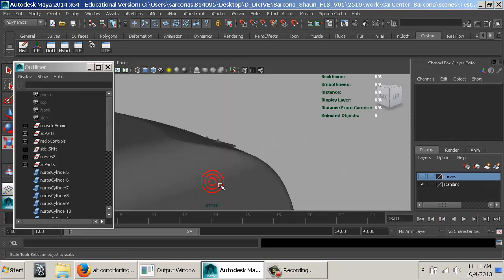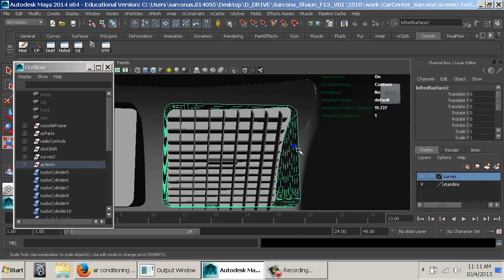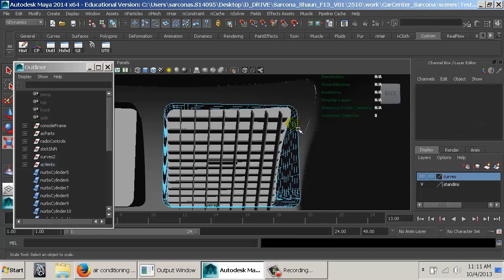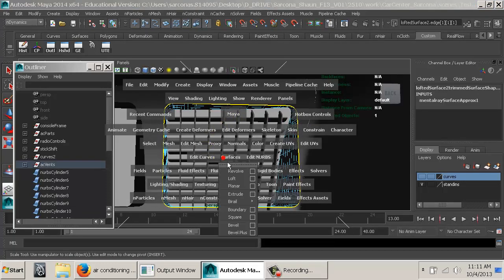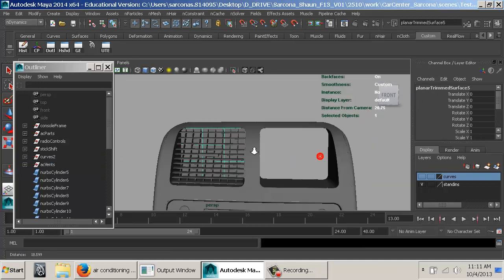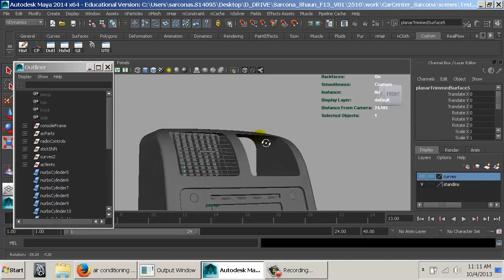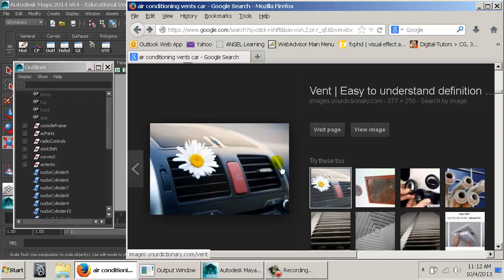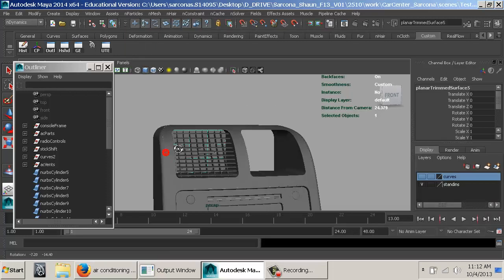Okay. So let me close the back of this off. I'm just going to go to Trim Edge. I'm going to click on the Trim Edge and say Surfaces Planar. There we go. That's a much easier way to get that. Okay. So now we have the vents done. There's other stuff that would be inside here. We just can't see it because it's so dark.